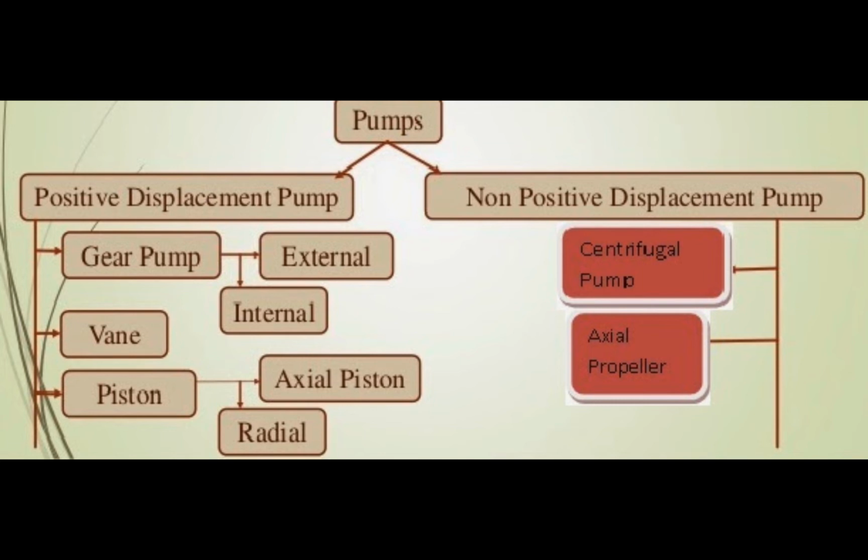What are two types of hydraulic pumps? Hand pump, power pump. Positive displacement or non-positive displacement. What is the purpose of the shearable section in a hydraulic pump? Disconnect the pump. If the pump seizes, the shear section disconnects.